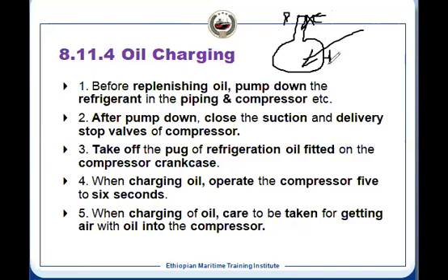We have connected this with the pipe and the container. This container is supplying the oil. Now this valve is shut. Once you see the pressure has dropped, you stop the compressor, then you open this valve, because this is filled with oil, and this container should be a clean container. There should not be any contamination when it is entered, and there should not be any air also entering it.